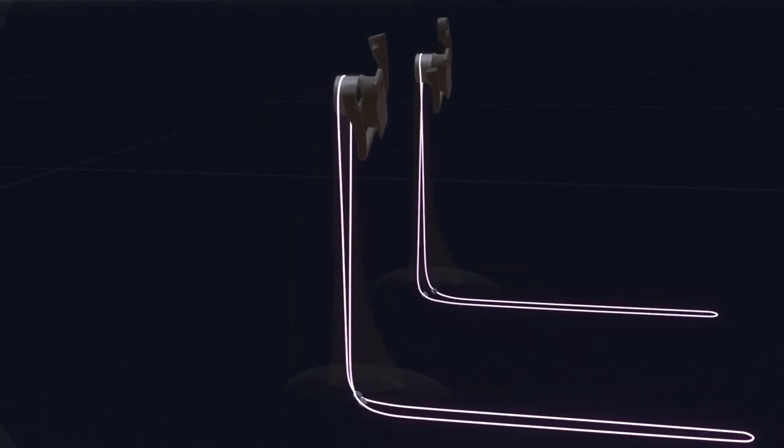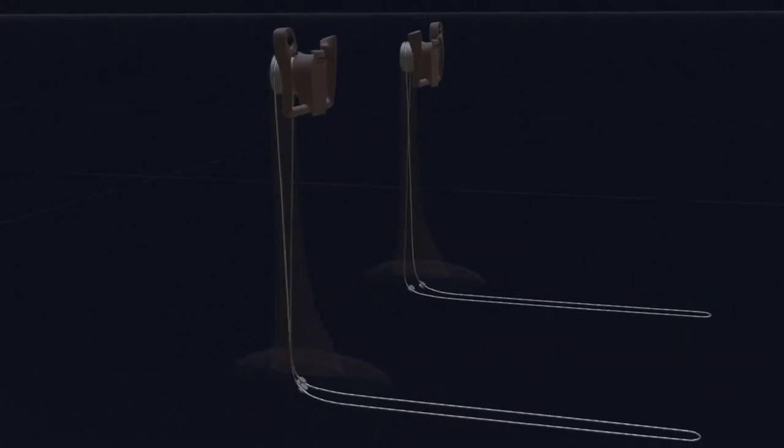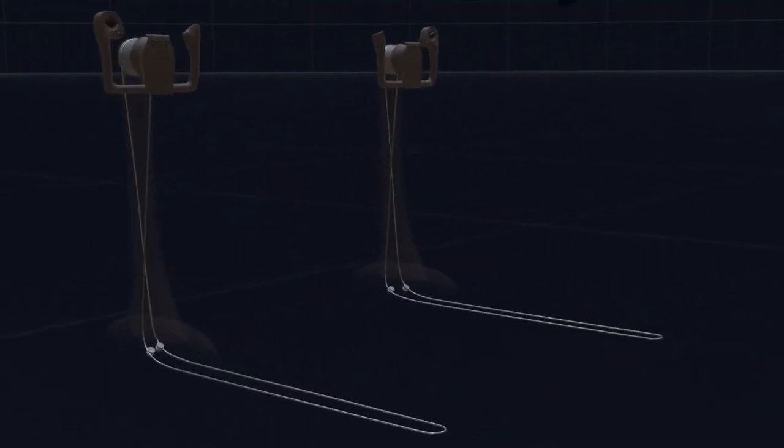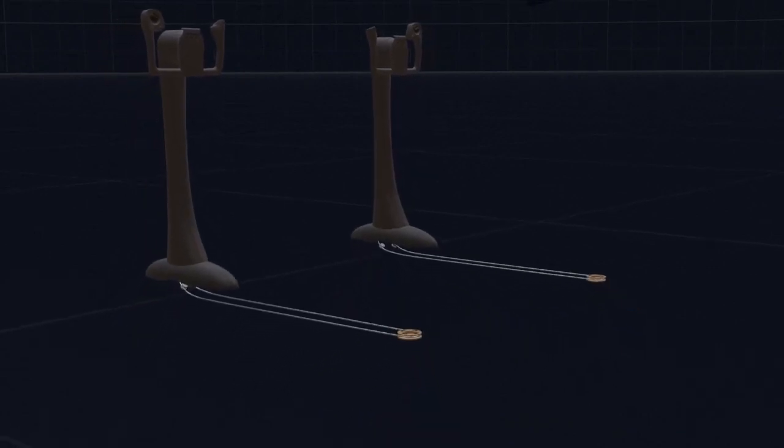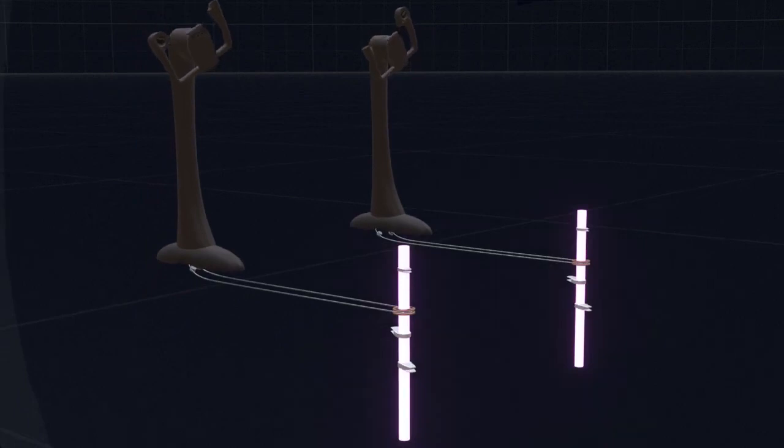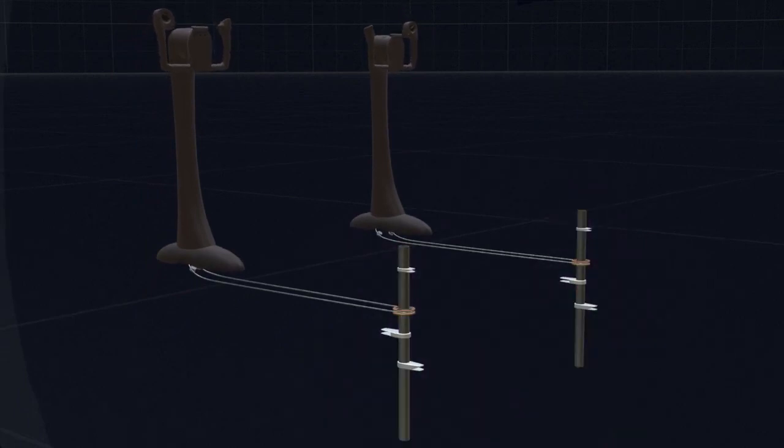Control wheels are used to give a left or right roll command. When rotated, the wheels move the control cables. The cable movement rotates the cable drums. The drums rotate the left and right shaft assemblies. The two shaft assemblies are connected, so the rotation of wheel on one side transfers the movement to the other wheel. This ensures both the pilots have indication of aircraft roll command.